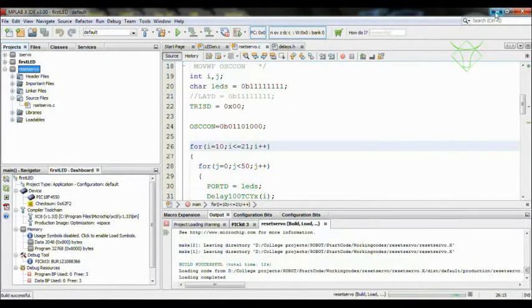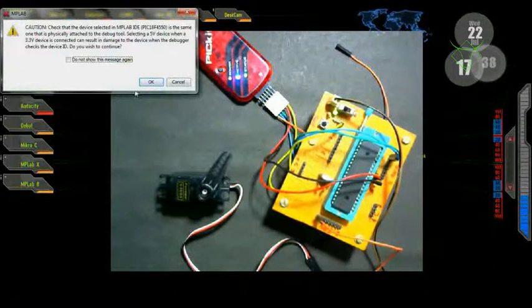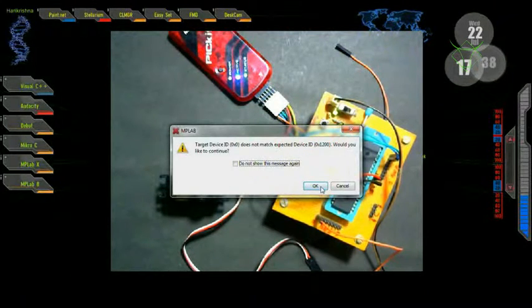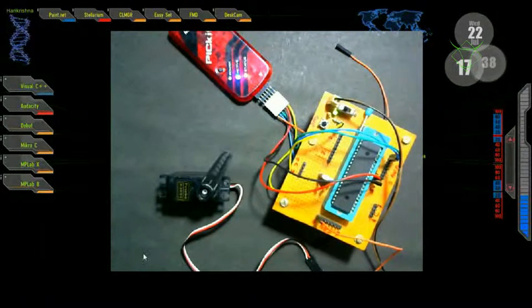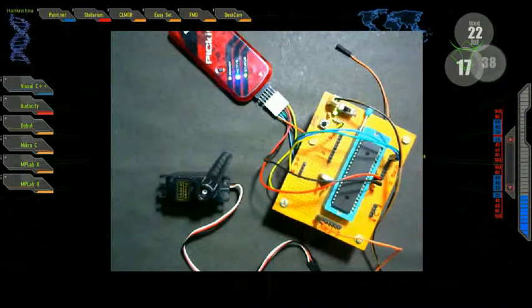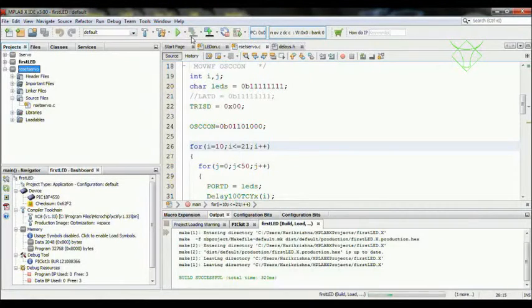These kinds of boards are a little messy. You have to keep connecting and disconnecting the line sometimes. And I don't know, for some reason PIC18 doesn't accept this voltage. I mean, it doesn't directly program. You have to supply an external power supply and then only program. Some glitches will be there, so be patient, and let's try this.